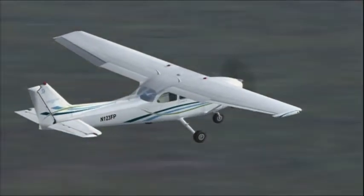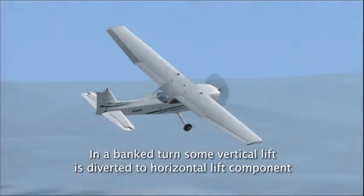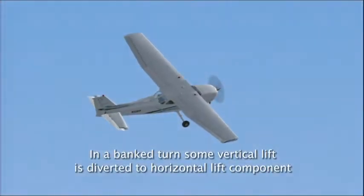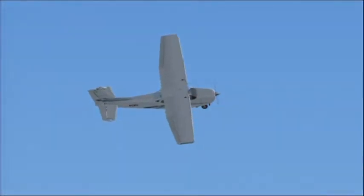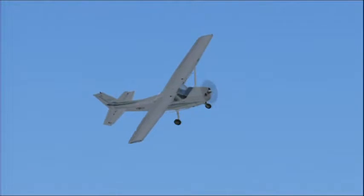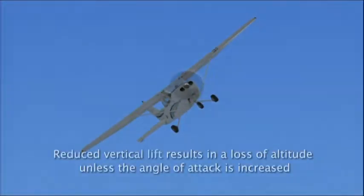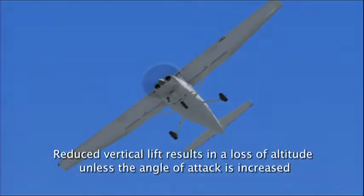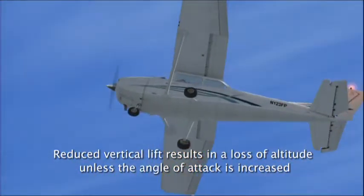When an airplane is banked into a turn, a portion of the vertical lift being developed is diverted into a horizontal lift component. It is this sideward component that forces the airplane from straight and level flight and causes it to turn. The reduced vertical lift component results in a loss of altitude unless total lift is increased by increasing angle of attack, increasing airspeed, or both.